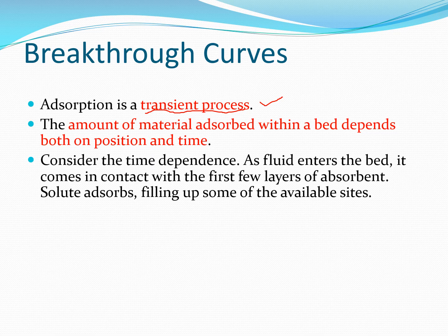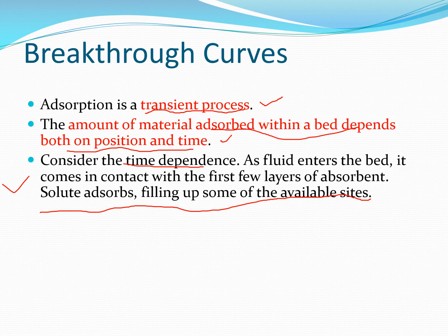Let me explain further. The amount of material adsorbed within the bed depends on both position and time. So consider a time dependence. As fluid enters the bed, it comes in contact with the first few layers of the adsorbent. Solute adsorbs, filling up some of the available sites. Consider that you have just entered the feed into the column at time 0.